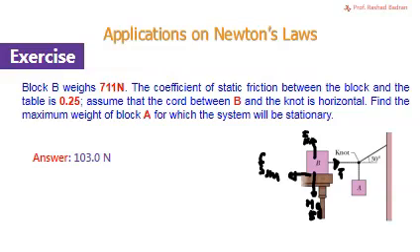That's why when we said this is Fs maximum, the weight here is considered as a maximum weight, because we need to overcome the maximum static force of friction in order to get this on the verge of slipping, while the mass A is going to be responsible for pulling the whole system on the verge of slipping. Now this is the whole forces on B.